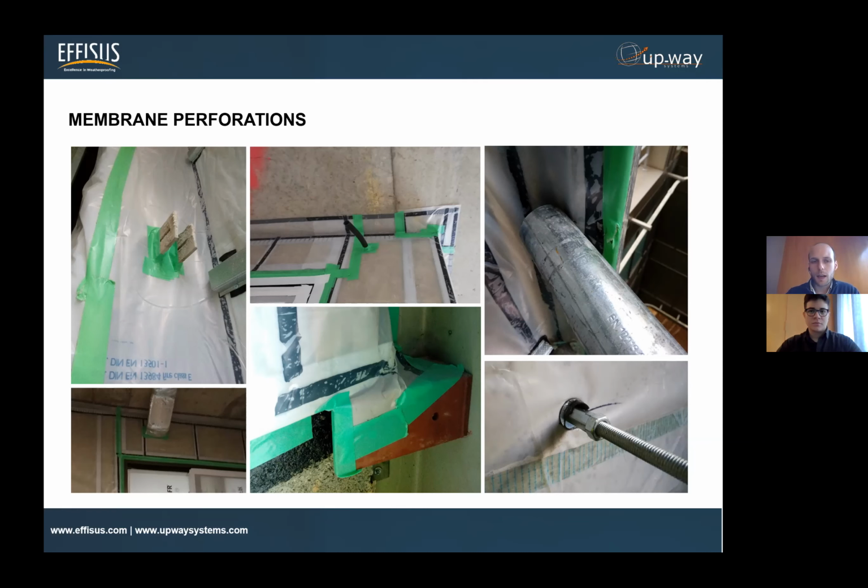So when we are supporting architects and consultants through the design stage regarding VCL, for instance, or the full system, we would be asking for this kind of details as much as possible, so that the guidelines we provide to the site already predict this kind of perforations, even if we do not have very accurate information about how many, what's the dimension, etc. If we find some, we will already be aware of how to deal with them.